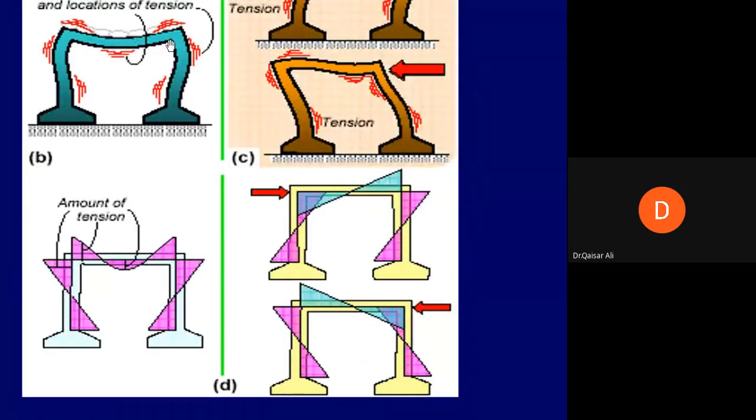This is also possible sometimes. Sometimes in a very high seismic zone, you get a bending moment on the bottom side of the beam at the end of the beam, at this location, where previously there was no reinforcement requirement. It is possible that in high seismic zones, you come across a bending moment which is higher than the bending moment at the midspan of the beam, resulting in more reinforcement on the bottom side of the beam at the ends than the reinforcement placed at the midspan. This is quite possible in the high seismic zones.